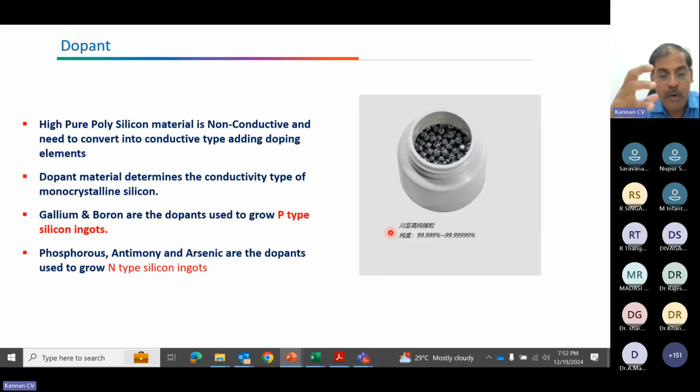So when you have a boron-oxygen pair inside the crystal as an impurity, it will deteriorate the minority carrier lifetime and the performance of the crystal quality, because the boron-oxygen pairs capture the minority carriers. So to minimize these boron-oxygen lifetime killing zones, industry started using gallium, where boron is completely replaced, so that there won't be any boron. Even if you have oxygen, since there is no boron, there is zero chance of a boron-oxygen pair which can deteriorate the minority carrier lifetime.